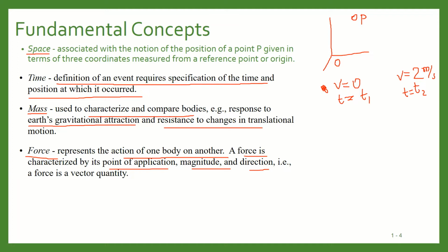So whenever you are talking about a force, you need to specify these three things: at which point your force is applied, what is the magnitude of that force, and what is the direction of that force. Only then you can know the effect of that force.